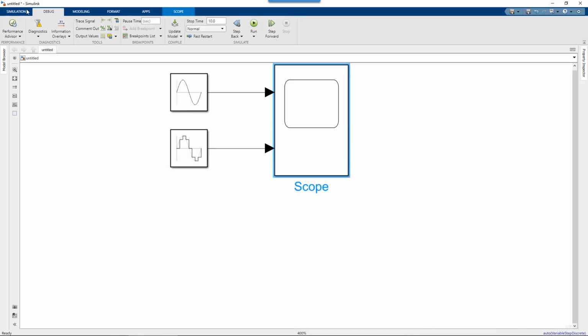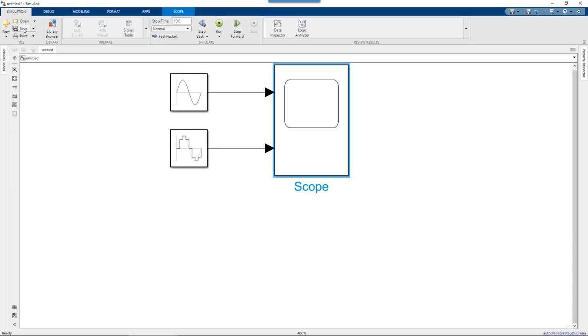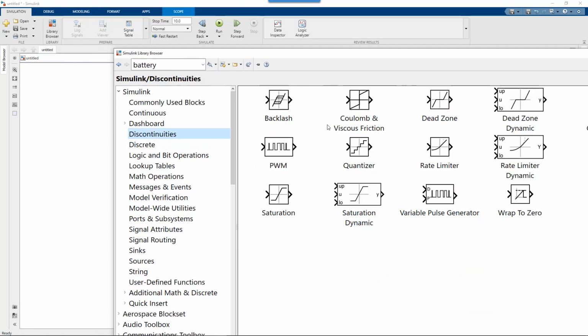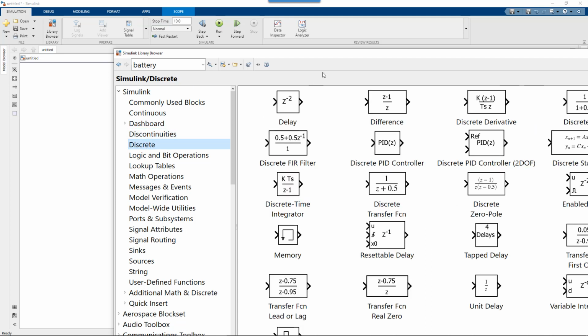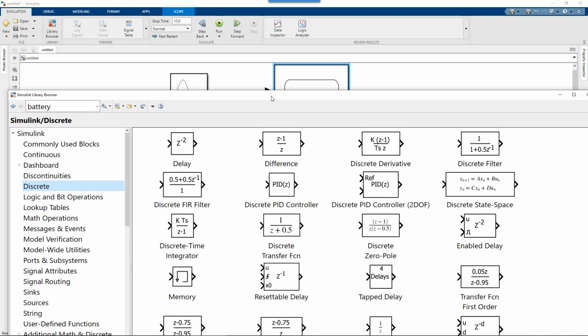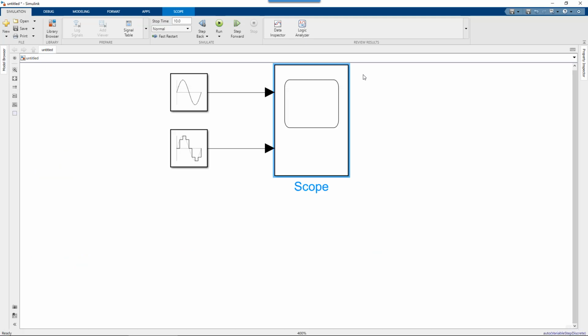You can actually do this if you do it more like a classical controls approach. They have the Z-domain blocks. So you can do it with Z-domain blocks, or you can do it more with just unit delays and basic logic, depending on what you're more comfortable with. I do recommend learning the basics of discrete classical control or discrete time signal processing because it will open up a lot of doors.